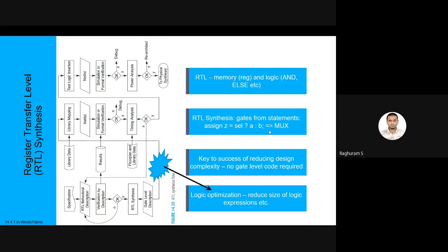I wouldn't call it intelligence, but you can call it a lookup table type of approach. If you have a select statement anywhere, the probability that the designer wanted a mux is very high. So whenever you see a select statement, RTL synthesis will put a mux there, and that is one way you can describe RTL synthesis, based on a lookup table type approach.